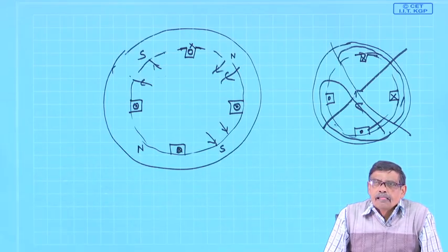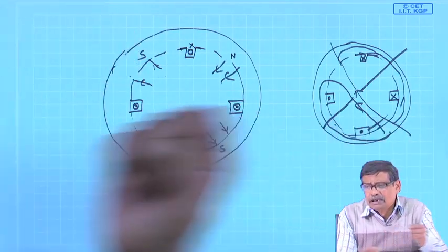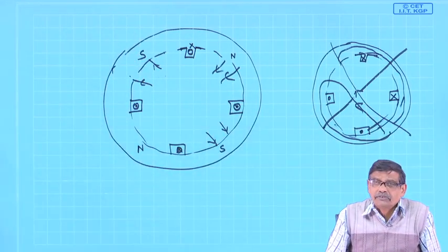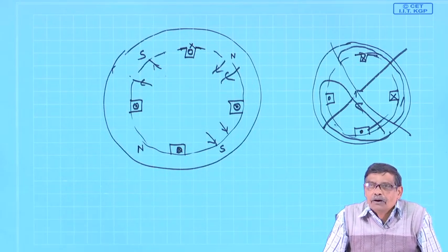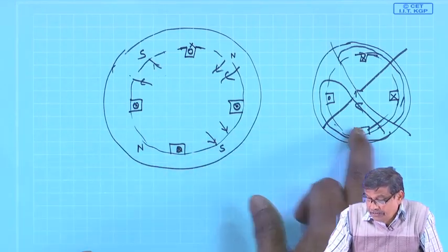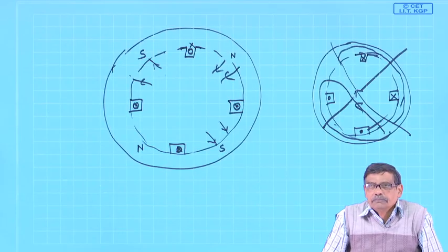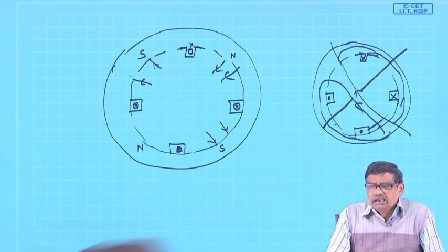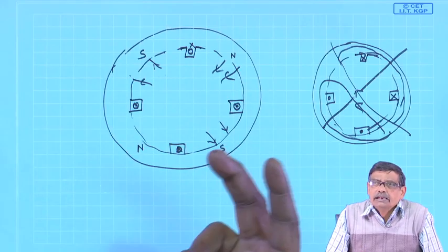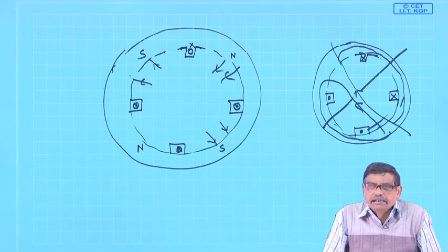But once again, many terminals have to be brought out from the machine, not simply 2 terminals for R phase, 2 for Y phase or 2 for B phase. To carry out this kind of operation, you require many terminals brought out, maybe from the groups of a particular phase. So, it was cumbersome, and you have to change that interconnection only to get 2 levels of speed, that is all, with a cage rotor.